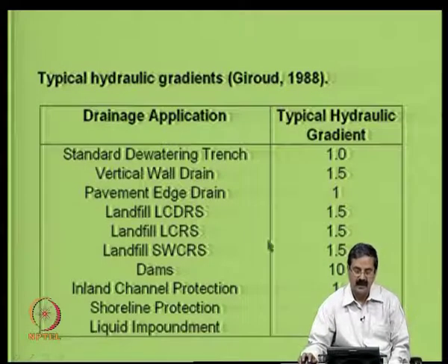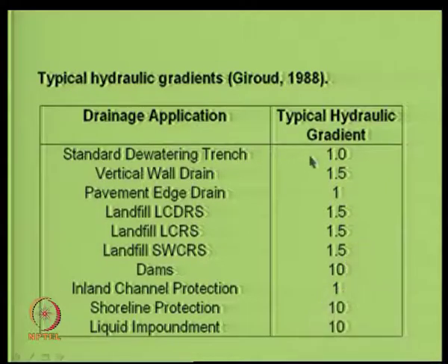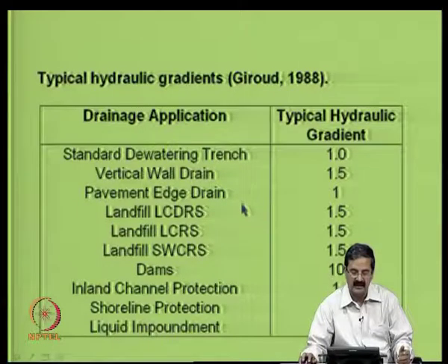design procedure. Some of the contributions in this method are that they clearly highlight what are the gradients that are there in different types of geotechnical structures. Like it can be very high in the case of dams, where the flow is more if the hydraulic gradient is more, and in other cases like trenches, the hydraulic gradient is less. Some of these factors have not been addressed in the earlier design procedures, whereas some of these ideas on gradients are to some extent incorporated in this design.